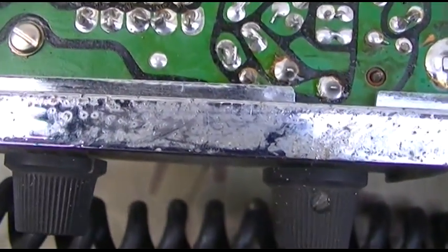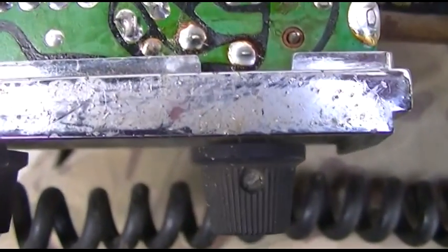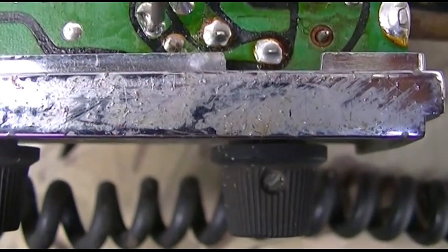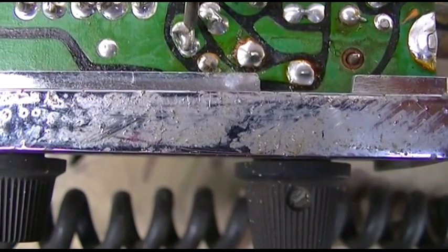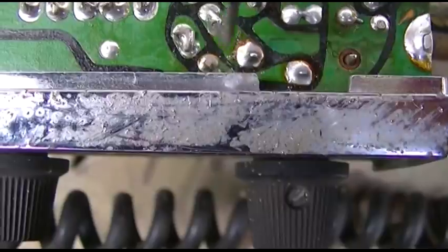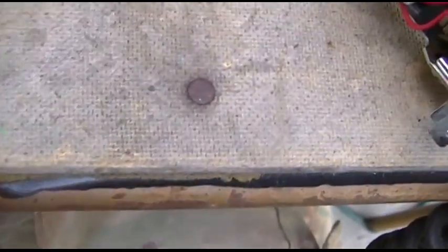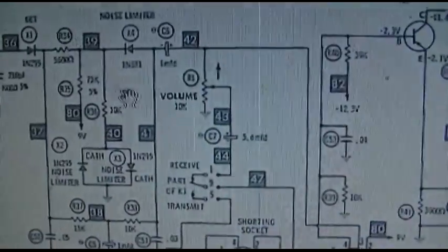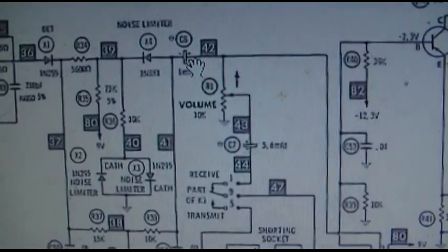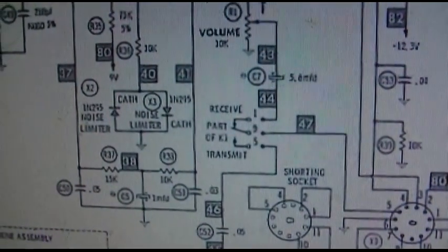And the level of noise is the same on both sides when the guy was talking. Let me see if I... I heard somebody coming back. So it's obviously not that capacitor. Now we got another capacitor in here that was going to ground, which could be shorted. Let's see, this capacitor's, I'm not going to say it's good, but there's audio on both sides of it.